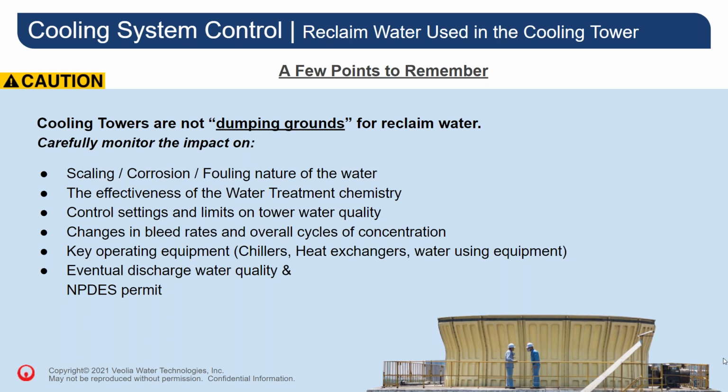What's its quality? It should be pretty clean, right? I mean, as a matter of fact, it should be pretty close to distilled water quality. Maybe it could be, but maybe it's not. It still can impact your tower's water treatment, either positively or negatively, depending upon how you adjust. The stream could still contain volatile organics that could present food sources for microbes where you need to adjust your microbiocide feed. That needs to be understood and accounted for.